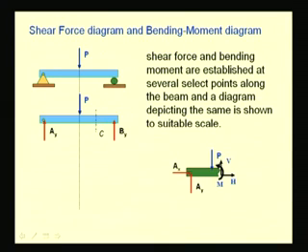So, this is a free body diagram of the portion of the beam AC. We have this shear force, the bending moment and axial force, if any, in the positive convention. For this case, since Ax is 0, the axial force H is also 0, and we have only the shear force and bending moment as the internal forces.